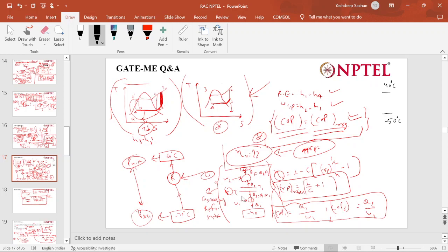Yes. If something is not clear, I will repeat some important parts again. If anyone has any doubt, let me know, then we'll start that problem. So here, simply, we are dividing one refrigeration system into two refrigeration systems: one from minus 42, let's suppose minus 10 degrees Celsius, and the other from minus 10 degrees Celsius to 40 degrees Celsius, instead of going from minus 42 to plus 40. Clear? Is it clear to everyone?